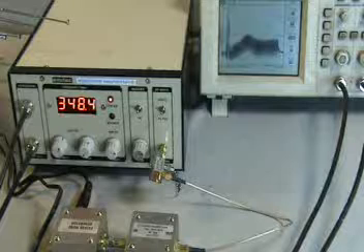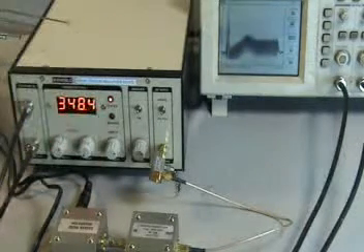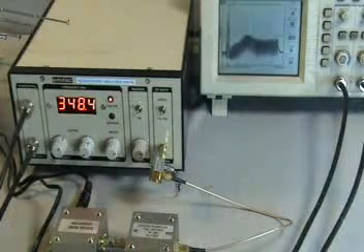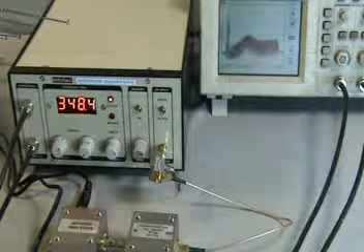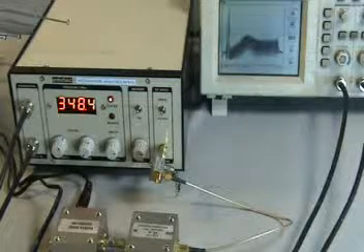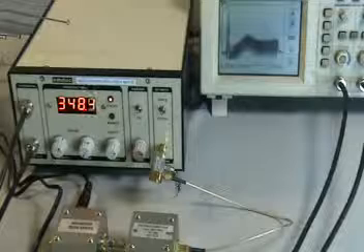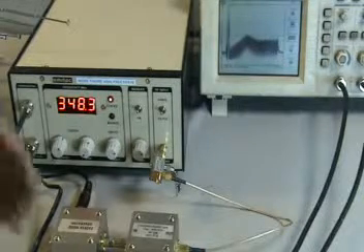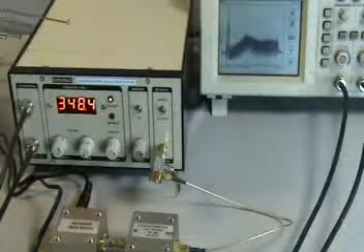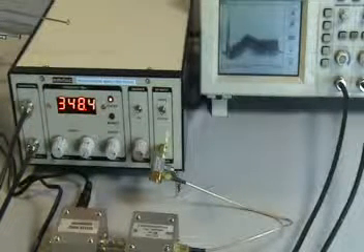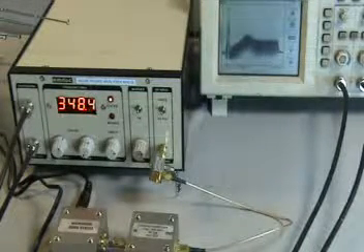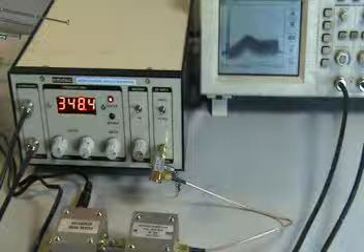Now what we are trying to observe is that in order to keep the noise figure of a subsystem or a device chain to a minimum, we need to match the system impedance to the normalized impedance of 50 ohms. So we need to keep the input impedance and output impedance in all the subsystems equal to 50 ohms. For this particular purpose, this noise injector cum coupler cum impedance analyzer has been provided.